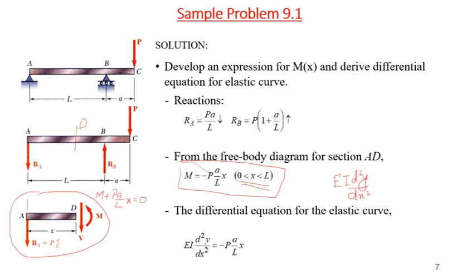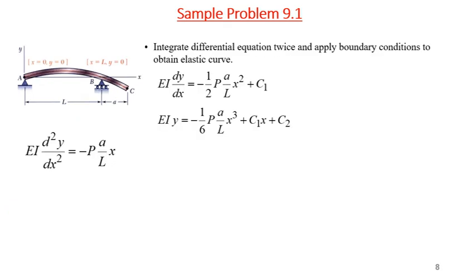the equation of moment in terms of x. So we put the value, and this is the differential equation of the elastic curve. Now we integrate it with respect to x, and we get this value, and again we integrate, so we get C1 and C2.